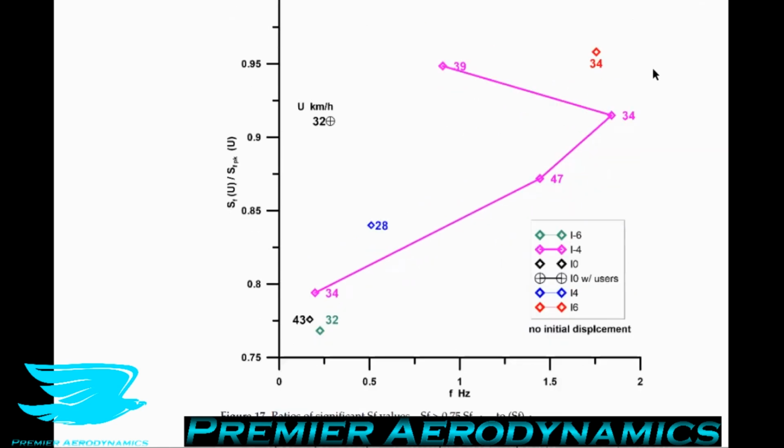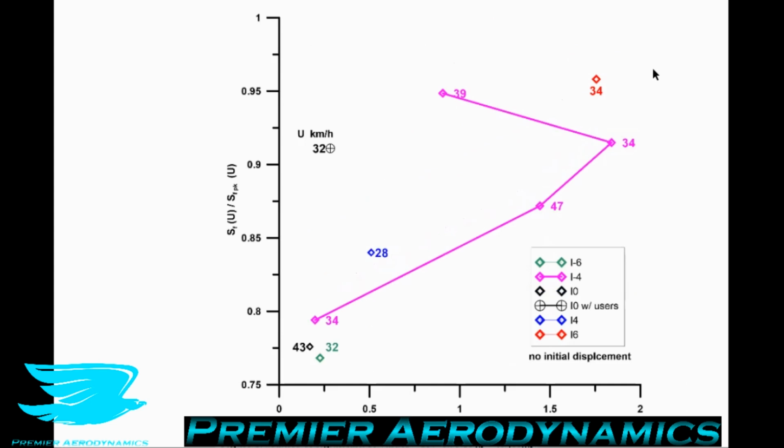So in figure 17, we have the spectral peak component. The spectral peak component corresponds to a frequency that is always close to the first mode and to all other significant modes, with a spectral content below the peak occurring for wind velocities above 30 km per hour. Within this group, most of the high spectral components occur for frequencies clearly above the fundamental mode. The fundamental mode was 0.166 hertz. So they are clearly unable to excite the instabilities.